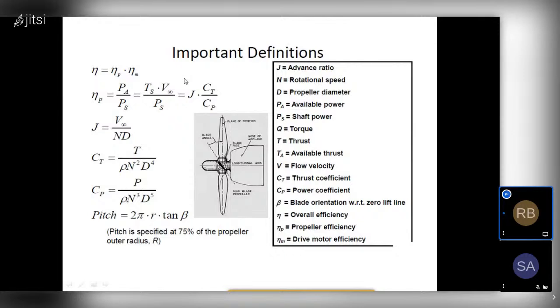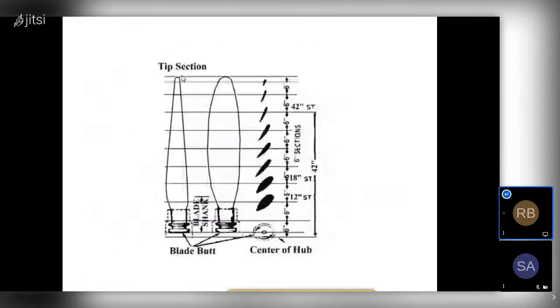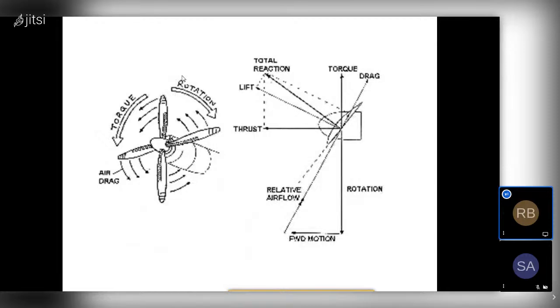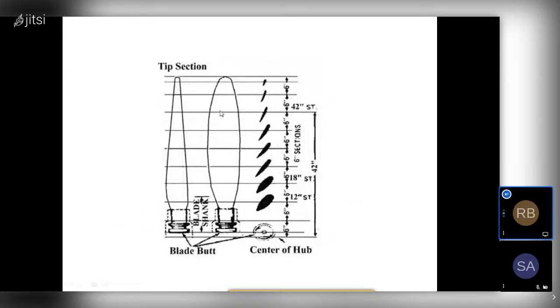And here we even have the lift and drag distribution as shown in this slide. Instead of CL and CD, it is convenient to specify a radial distribution of polar and design angle of attack. So the distribution of CL and CD can then be examined. For good performance, L by D should be high. Also, it is better to use a low angle of attack for design. So the tip section, root section, the cross sections from this end to this end, that's also very important.